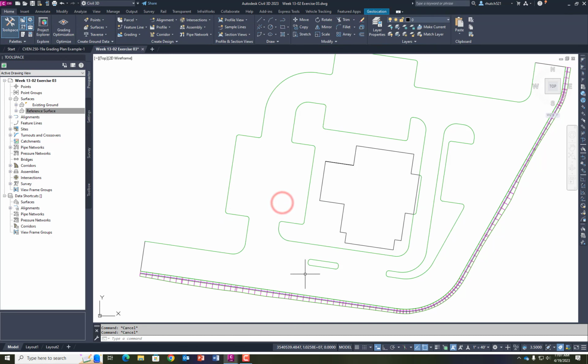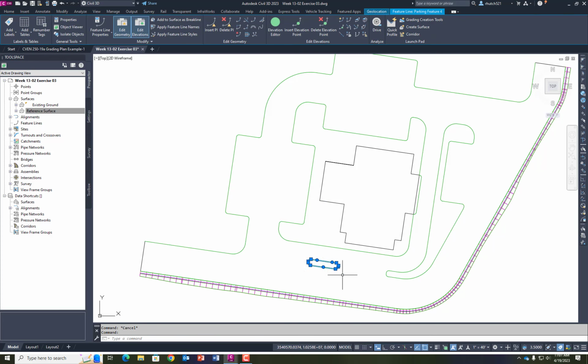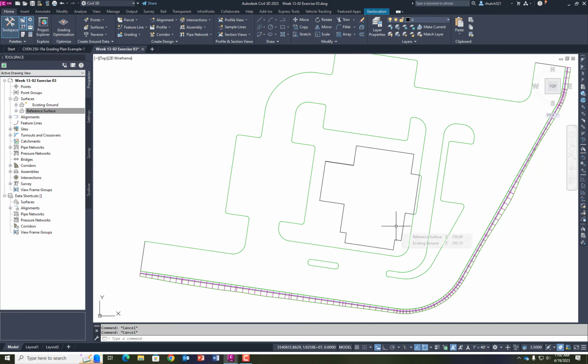You can also use it on the contextual ribbon. So if I select this, this is the button that reverses. So I can click that as well and click this as well, and that will reset all those. So that's the two ways you can reverse a set of lines. So now that they're reversed, let's add them into my existing corridor.